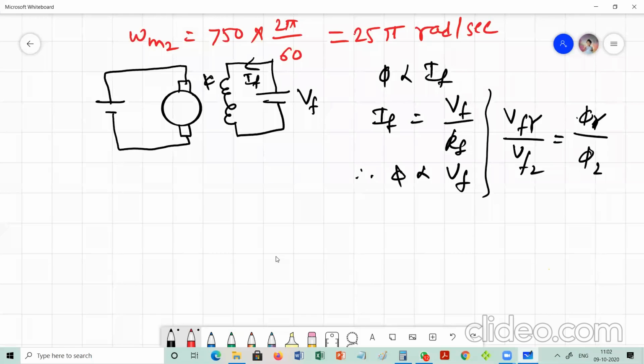One point is common between the armature voltage technique and the field current technique, where the speed is rated. When the machine is running at the rated speed, that was the starting point for the field control technique, but the end point for the armature voltage technique. That is the common point between both control techniques.